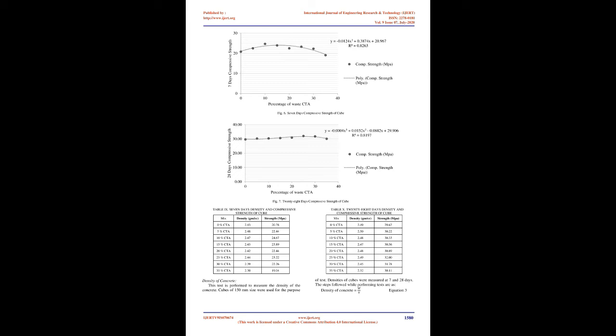The procedures followed can be listed as 1. The specimen was removed from water 24 hours prior to test and let dry in air, and weight of the specimen was measured. 2. The bearing surface was wiped off and cleaned off the loose particles which are in contact with compression plates.